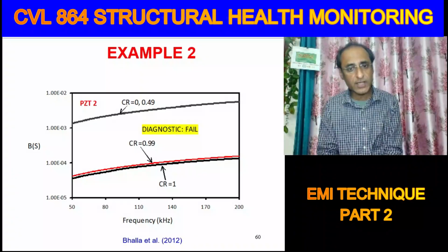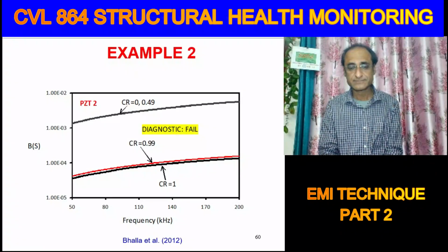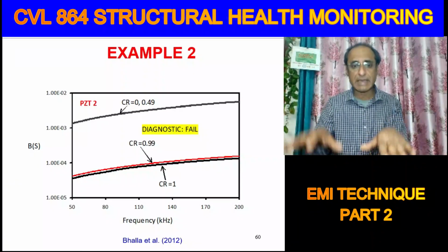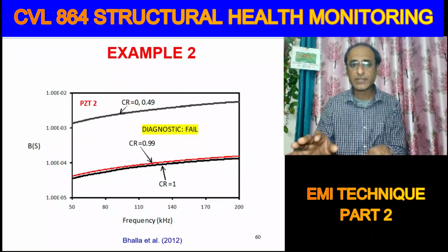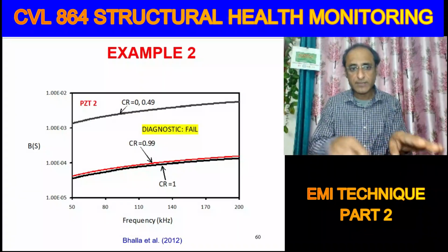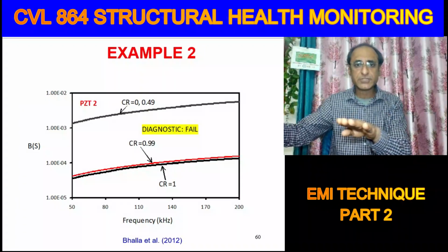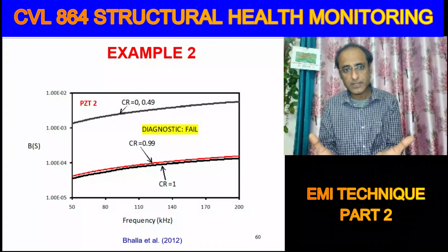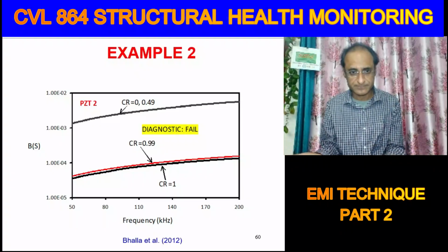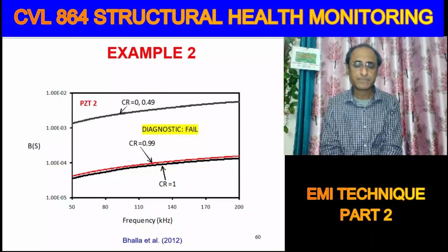But what is the reason here? Is it debonding or is it damage to the piezo patch? Damage. Yes, damage to the piezo patch. So naturally the capacitance goes down. So that means the patch is broken into two parts. If there is a crack, it means that one part is lost as far as the electrical circuit is concerned. So everything becomes smaller. So here is a case of damage to the piezo patch.